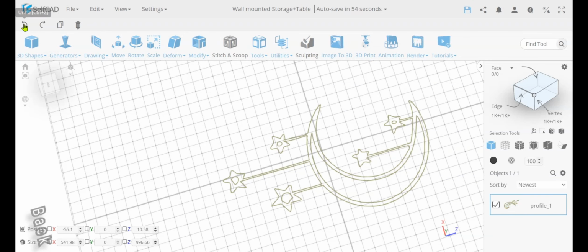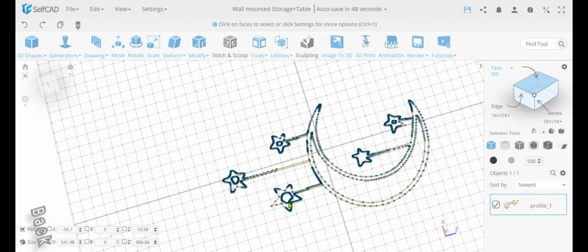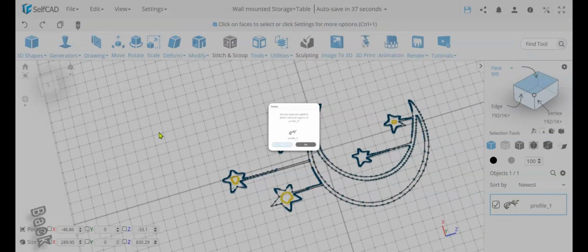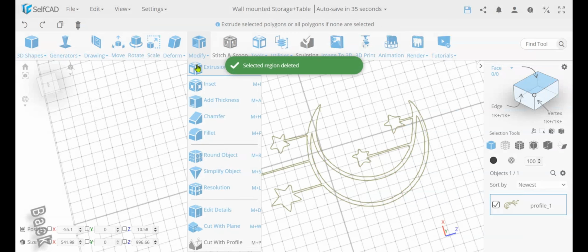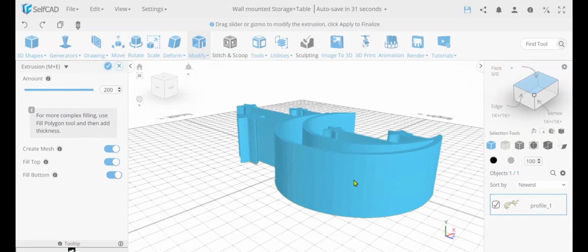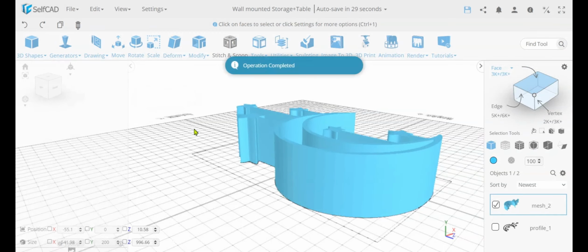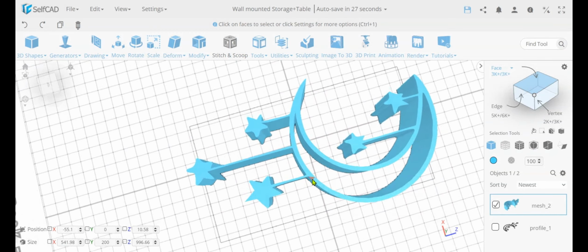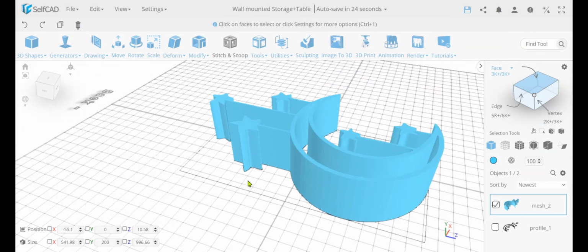That could be done. Probably the easiest way is to do it on the SVG directly. So if I take this inside shape, I can select them and simply delete them. So I'm going to take these inside, delete them, and now let's use extrusion. And as you can see, we get a much nicer, clean view that we got with Image 3D. So in this case, it's just converting it to SVG and then simply using SVG.